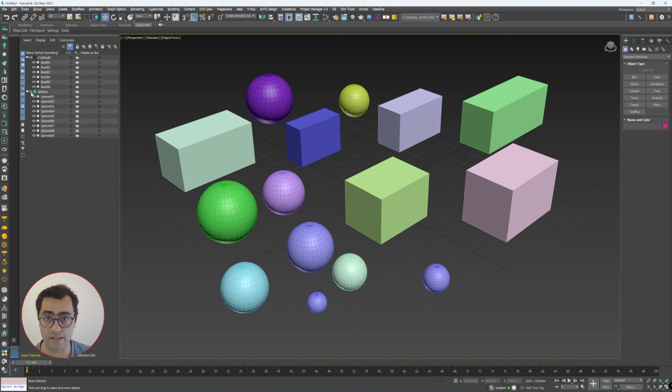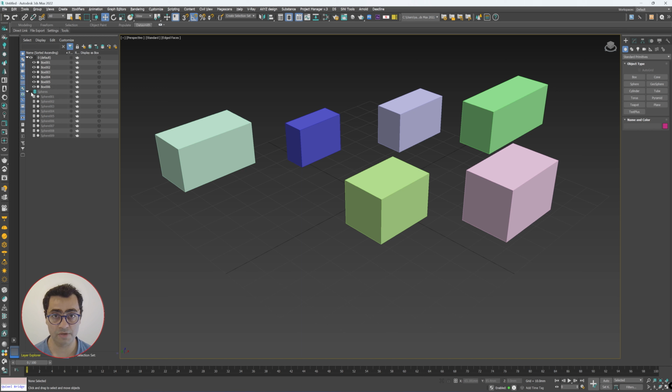The other bit you need to remember, most of the newcomers who experience 3ds Max usually get confused by this quite a bit. For example, right now the default layer is off. At any moment now, if I try to create a new object here, it's going to throw up a warning saying objects cannot be created on a hidden layer. So what do you want to do? You want to unhide the layer or abort object creation? Before, there was no check like that.